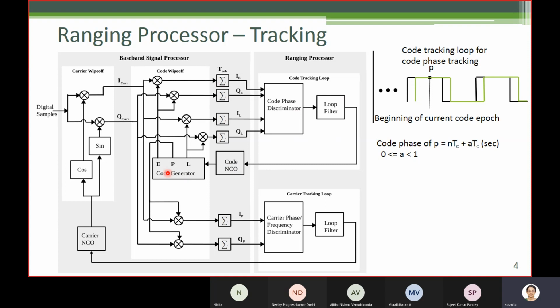The code phase generator, once acquisition is successful, is started with the corresponding candidate value of CP. The candidate value of CP which gave the maximum correlation amplitude is taken and used to start the code generator. Similarly, the candidate value of the Doppler corresponding to the maximum is taken and used to generate the replica carrier here.